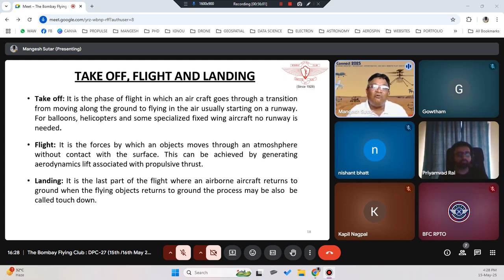No longer is it counteracting gravity. So gravity is overpowering the throttle, and because of the weight of the drone, it will start slowly coming down. You have to manage that throttle so efficiently that you do a smooth landing, or smooth touchdown, what we call it. So that is your landing.